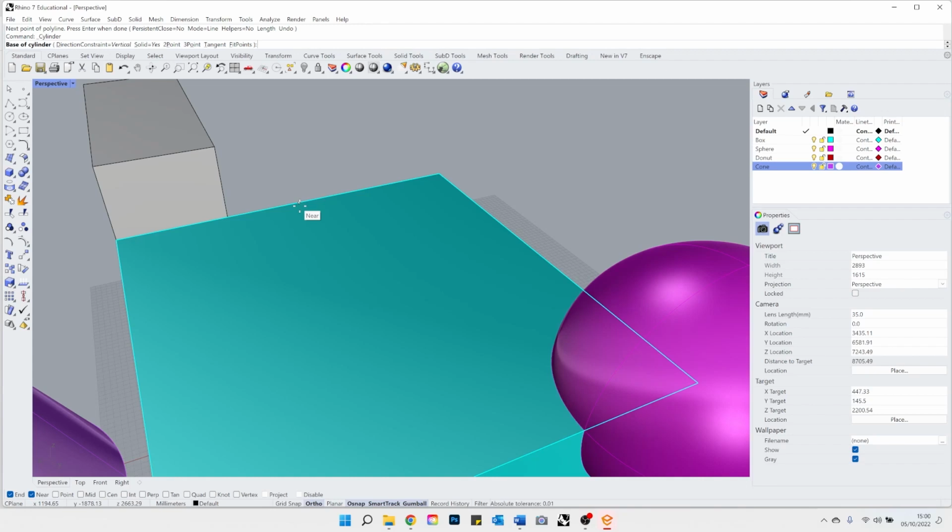Near is really useful, but it can get annoying if you have a lot of objects. If you can snap anywhere on the edge of an object, like the edge of a desk, but you also have an end snap on the corner, you can snap anywhere as close to this corner as you want if you have near snap on. It can be really tricky if you're not zoomed in enough, because instead of going to the corner, you'll be snapping somewhere on the edge. So only have near on if you need it. But the end snap, you're pretty much always going to have on.